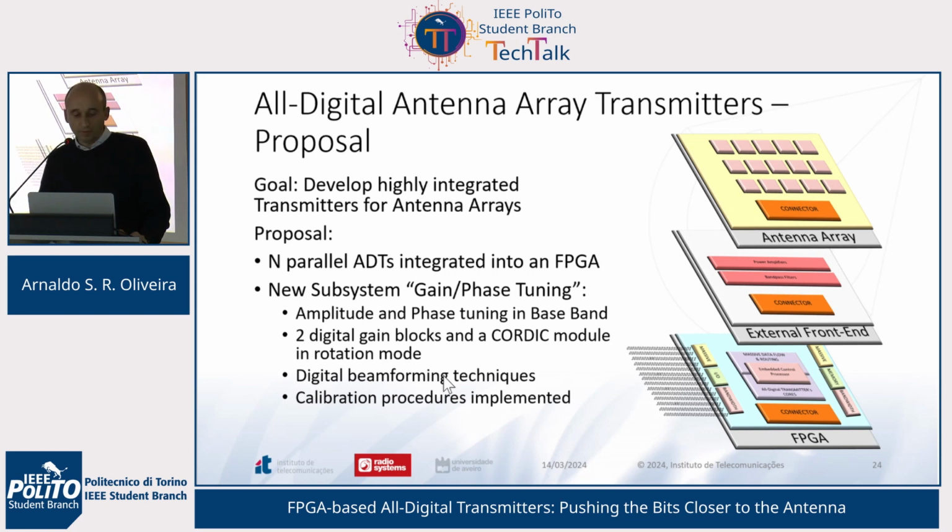This allows us to perform beamforming techniques fully integrated on the device, and this technique scales very well to a huge number of outputs because of the high availability of MGTs on current devices. But since we have multiple outputs and there can be mismatches in terms of delay, we also had to develop calibration techniques so that the beam is aligned to the direction we want.